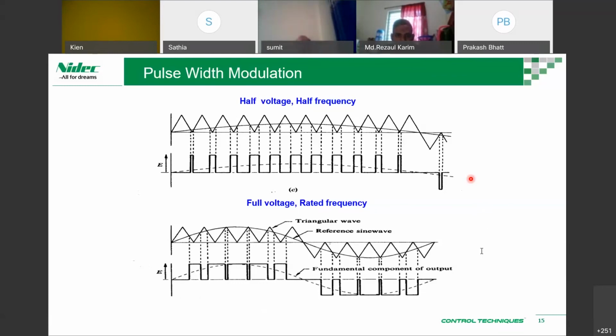So for open loop drives, we say we don't run less than 20 hertz or 15 hertz, depending on the environment, because of the heat factor. If you're running at 15 or 20 hertz or lower, the motor is running slow. Then if it has an inbuilt fan, you have a slow cooling factor. The fan is running slowly, heat dissipation is slow, and your motor coil is going to get hot faster. So that will damage the motor faster.